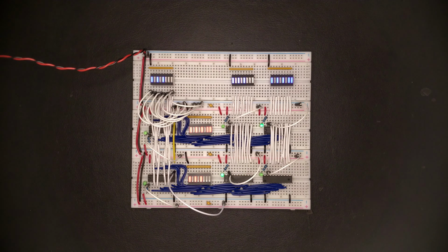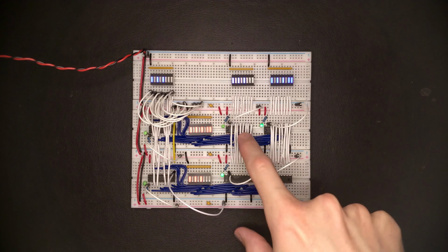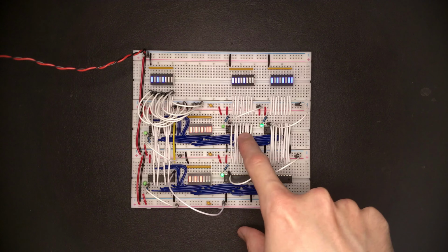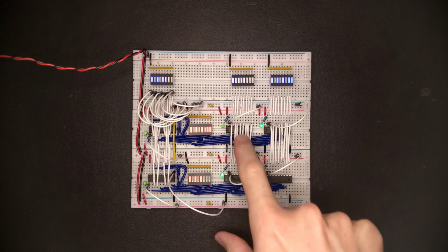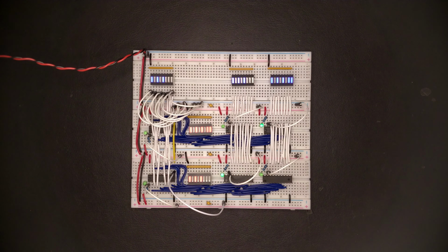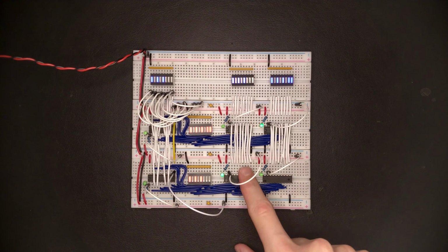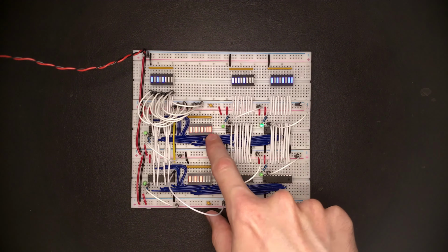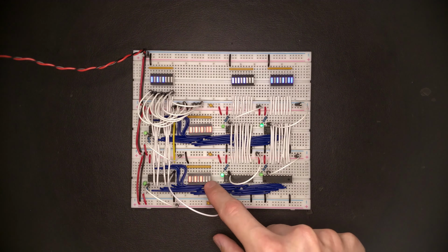Now the big danger and challenge at this point is these output enable lines decide whether a register drives its value onto the read data bus. But it's very easy to create a short circuit like this. For example, what happens if both of these chips have their output enabled? They both would take whatever's at the input and drive it onto the bus. But the first register has the least significant bits set to high, and the second register has them set to low.